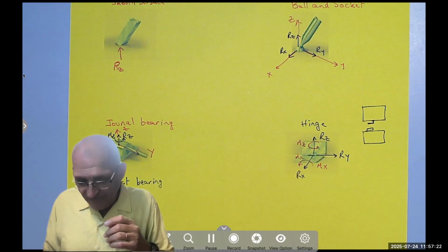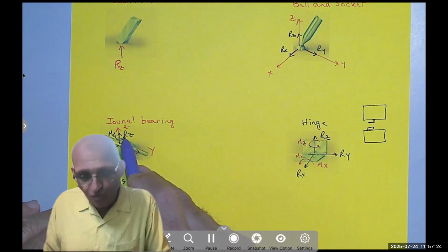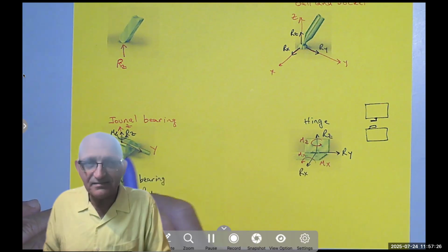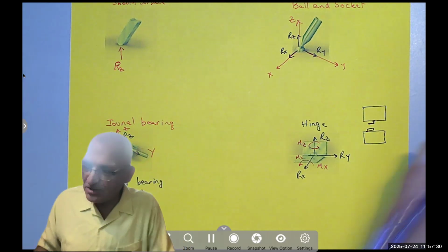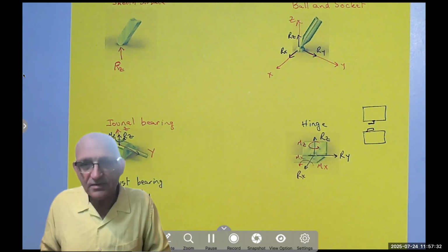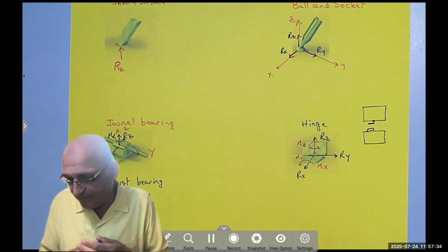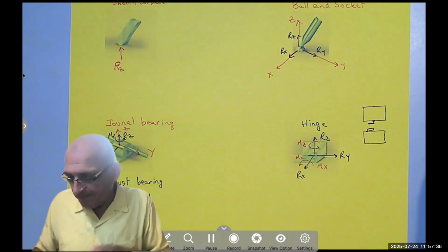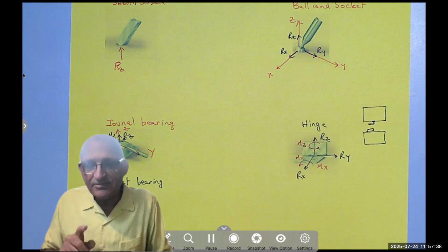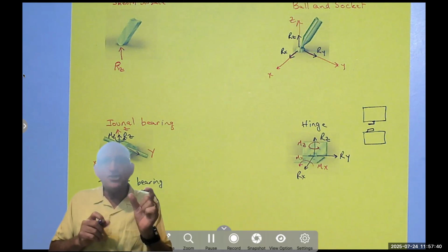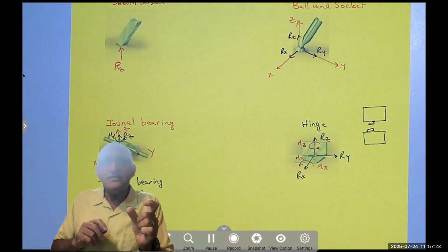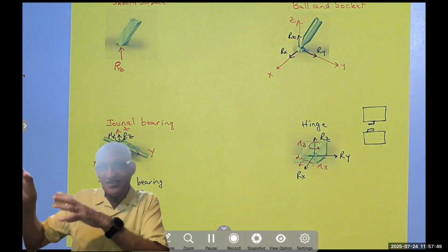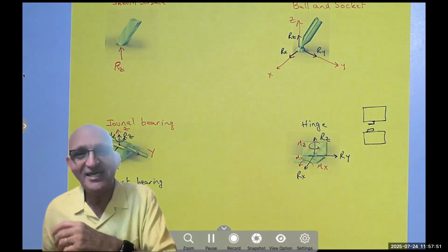Even these two moments, you can think of them as due to misalignment, or just, they prevent rotation anyway. But for the hinge, in many problems, you will see this term, the hinges have been properly aligned, meaning ignore the moments. So that's the translation from engineering to English.